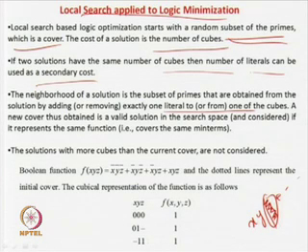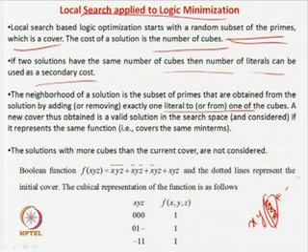We start with a given set of prime implicants, then what you do? So, the cost here is the number of literals, or the number of cubes that you can take. Now, you have to minimize. So, what you do? You remove one literal from one of the cubes. So, that is the next solution you can think. Okay, so, you are slowly moving in the solution space.